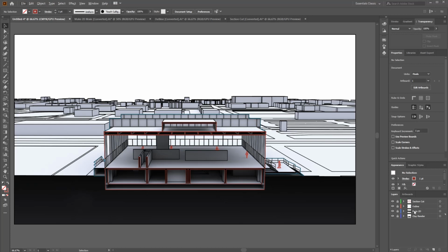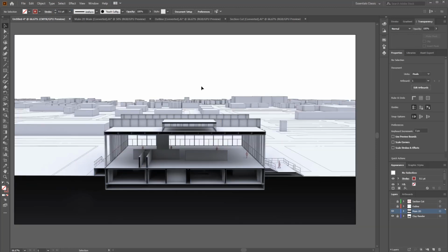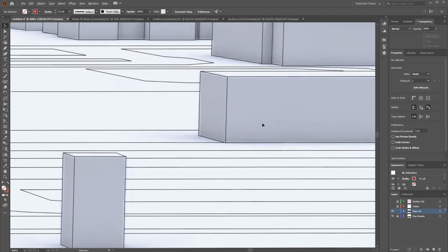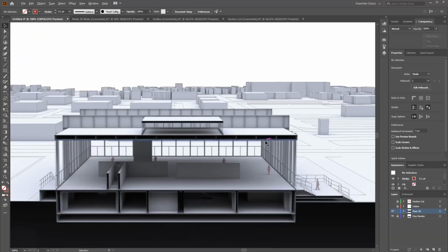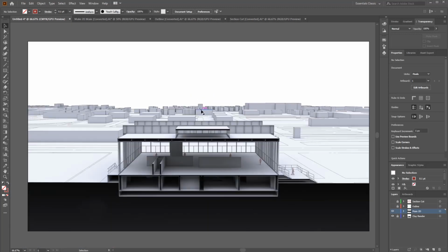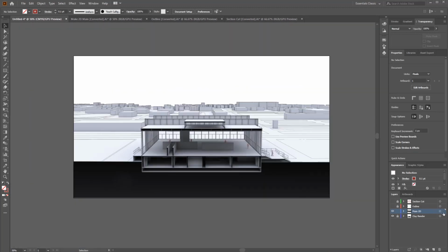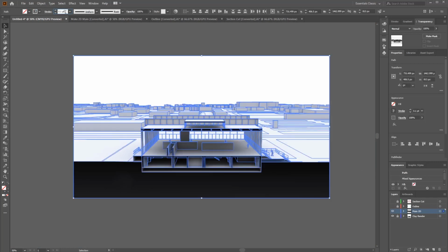So if you want to change that, all you need to do is first go to the main 2D layer. I'm going to select it, and then I'm going to use here a stroke of 0.1. Now you can see how all the lines became barely visible, and it's totally fine. It's up to you to control how thick you want the lines to be, but this seems to be a good approach. Maybe let's make it a little bit thicker, 0.2.